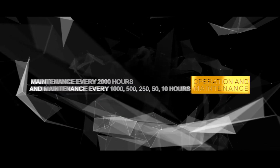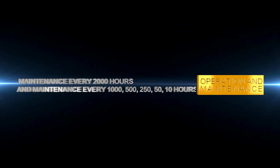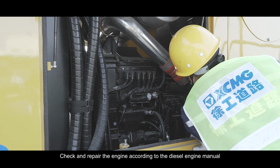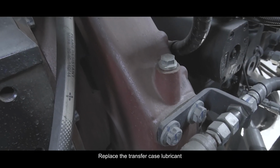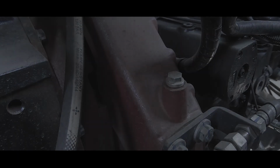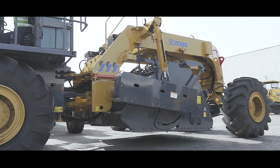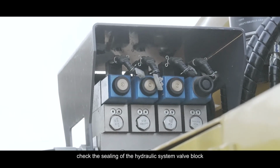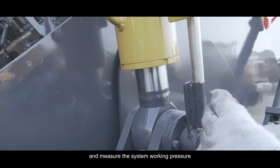Maintenance every 2,000 hours, together with maintenance every 1,500, 250, 50, and 10 hours at the same time. Check and repair the engine according to the diesel engine manual. Overhaul the gearbox and transfer case. Replace the transfer case lubricant. Through the natural descent of the working oil cylinder, check the sealing of the hydraulic system valve block and working oil cylinder and measure the system working pressure.